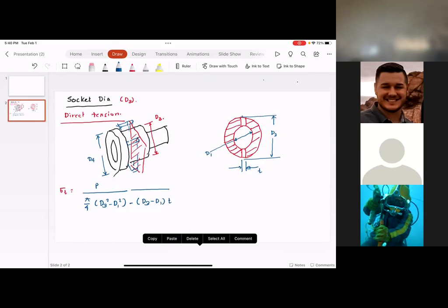So basically, you have to provide tolerances to the most important dimensions, and the most important dimensions are the dimensions that make up that assembly. For example, the rod diameter and the spigot diameter are the most important dimensions. If you look at the outside diameter of the collar or the thickness of the collar, they are not assembly dimensions. So this is another interesting question. Too much tolerancing is bad because it will increase the cost to manufacture, so you want to specify the tolerances that are essential for operation.